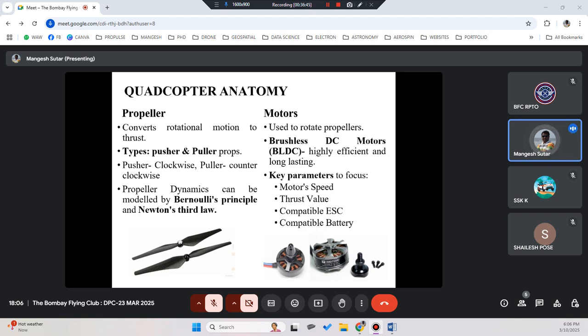So that's why it is not heating up very high. What is moving actually is the magnet around the armature. So as you induce the current into the coils, because of the difference in the magnetic field, it pushes the magnet further, based on the direction it is being made. So now north becomes south, south becomes north, north becomes south. So all these differences make the magnet move in a forward direction. That will make this motor move.